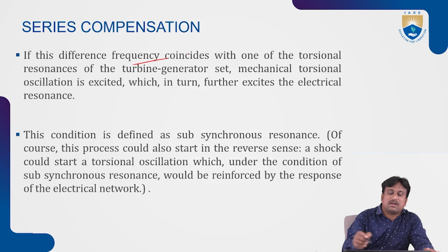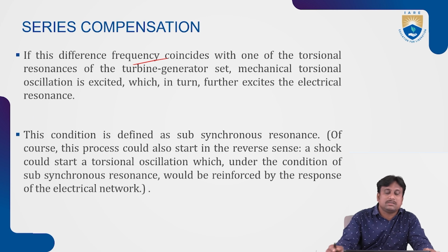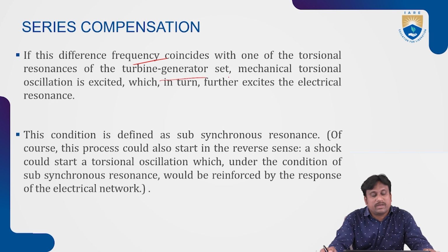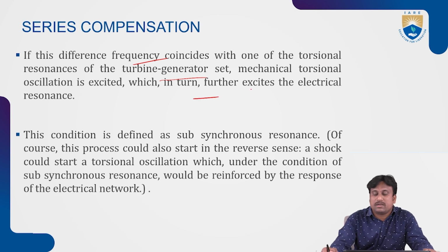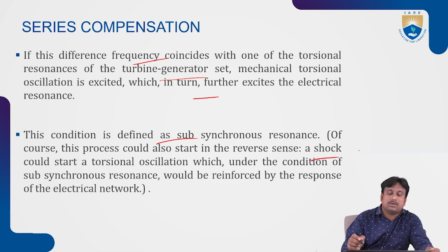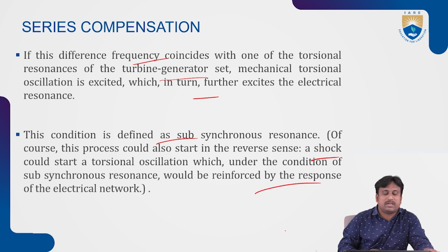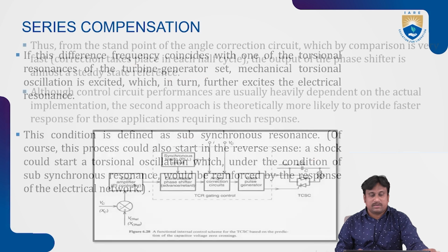So if this difference frequency coincides with one of the torsional resonance frequencies of the turbine generator set, the mechanical torsional oscillations get excited, which in turn further excite the electrical resonance. This condition is defined as subsynchronous resonance. Of course, this process could also start in the reverse sense. A shock could start a torsional oscillation which, under the condition of subsynchronous resonance, is reinforced by the response of the whole electrical network.